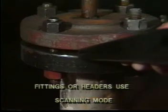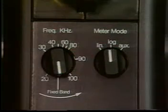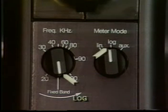To locate a leak in fittings or headers, use the scanning mode. With the Ultraprobe scanning module in the fixed band position and set at log, scan a general obvious area. Adjust the sensitivity on the Ultraprobe to focus in on the loudest point, moving from gross to fine sounds, or closer and closer to the leak site.